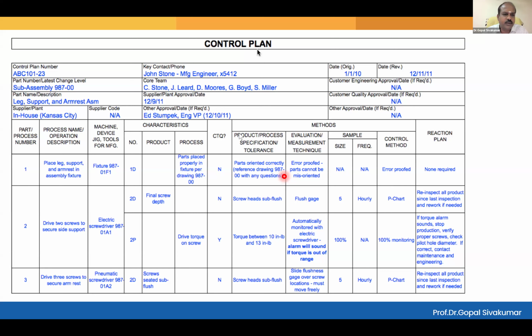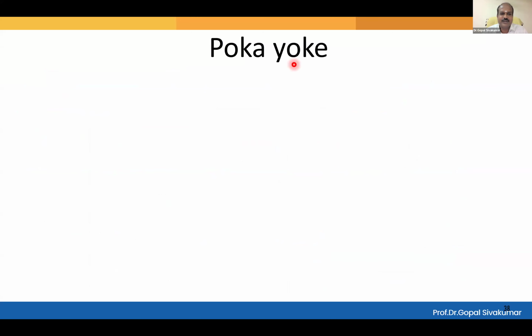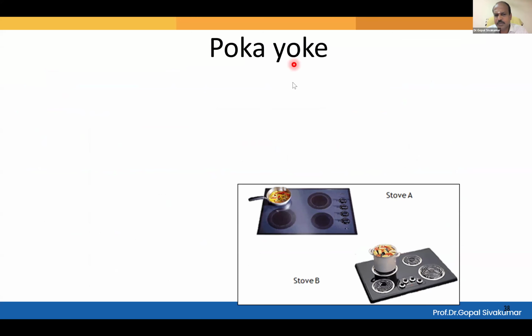And if you could understand reading out, yes, you read out. I'm not going to read it out. Right. All right. So another simple tool, Poka-Yoke. What is Poka-Yoke? It's a lean tool. It's a Japanese word meaning mistake proofing. Right. See, there is a problem here in the design of this stove. This is A, this is B. Which one has a better design? A or B? B. B. It matches the orientation. So the chance of wrongly operating an irrelevant knob is lesser.